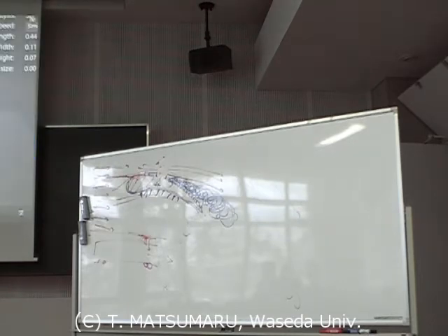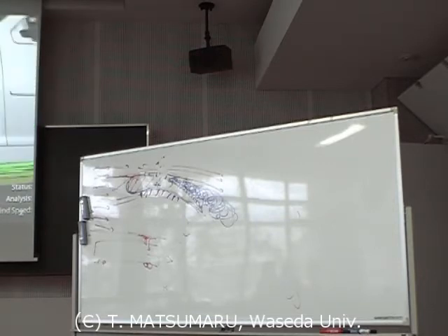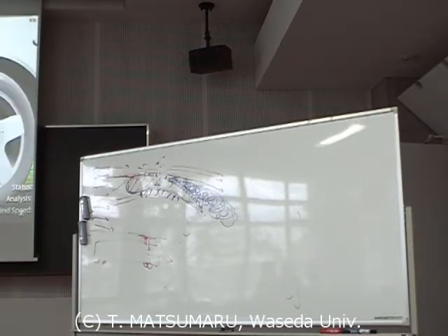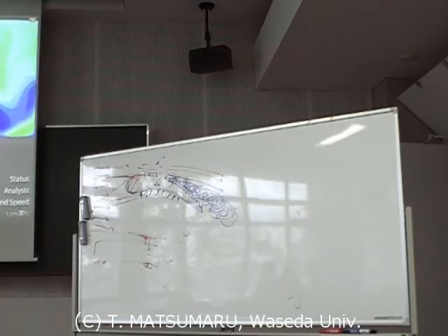Another way to look at it is that the air has mass, it has weight and momentum, and at the front of the object there's a point called the stagnation point, where the air is compressed and the velocity is brought to zero. It's like we are constantly grabbing air and pushing it with us. Similarly, the wake in the back is a low pressure separation bubble where we are grabbing a bunch of air and pulling it with us. We are giving it some of our energy and then letting it go, and then grabbing some more.